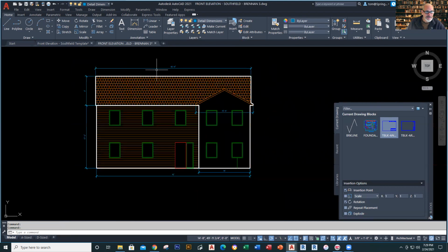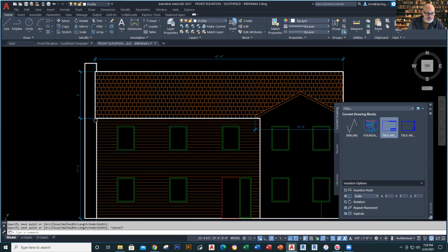That's normal. So I'll go ahead and make a polyline here. I'll go over here 2 feet, 2 feet, and then 26 feet 7, 26 foot 7, boom, which clears the house. All right, and then I'll go over 2 feet again, and then I just bring it down like that. And that's your chimney.